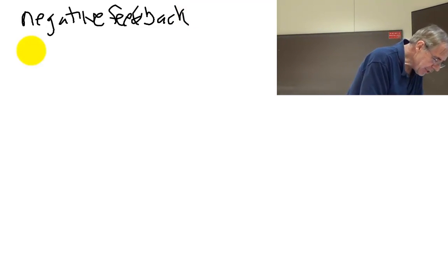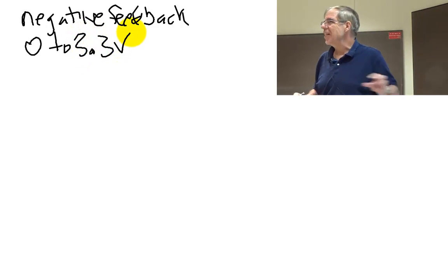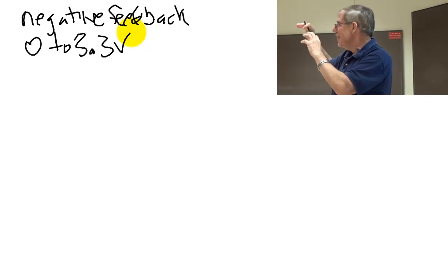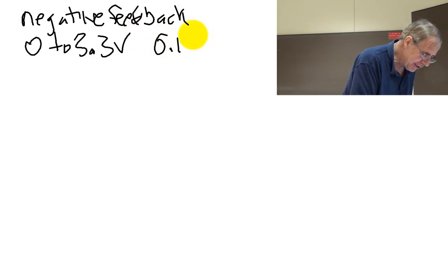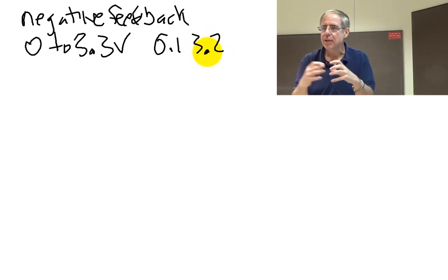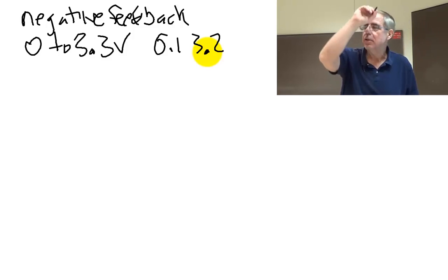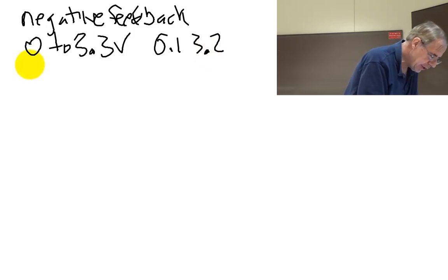Okay? It's rail to rail, which means all of my signals got to be between 0 and 3.3. It actually doesn't work quite perfectly near 0 or near 3.3. So, make them go from 0.1 to 3.2. If you want, a sub-rule to that. Okay, it works a little bit better if I go further away. Let's see, what was the next rule? Use the same order. No current.